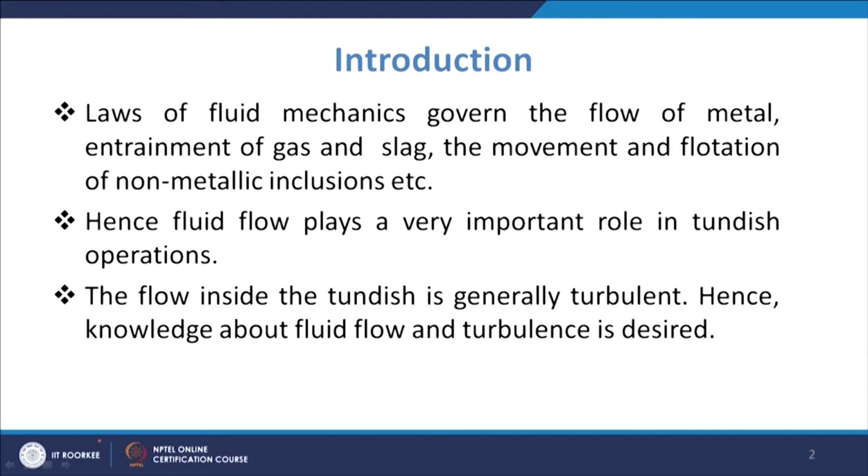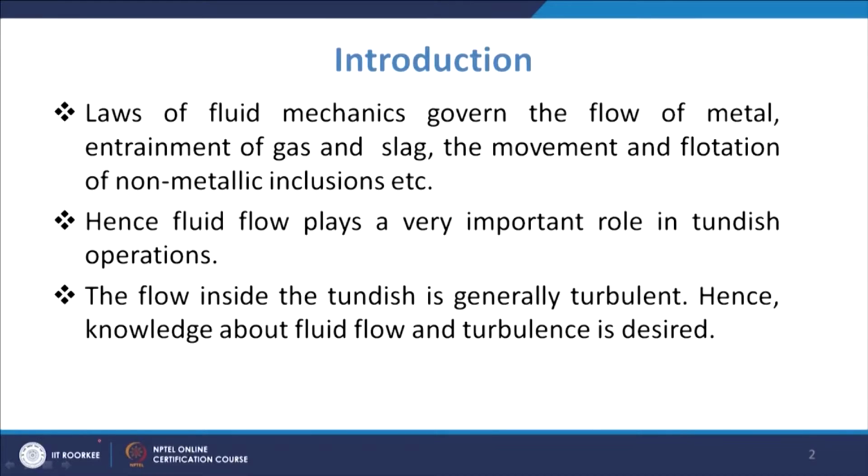So, as we discussed, in all these cases the laws of fluid mechanics which govern the flow of metal will be important, and that is why we need to understand the fluid flow behavior, especially if you talk about the tundish. In the tundish you have different regions. There is a region where the liquid metal is coming from the ladle, and then you have the remote regions also. In most cases, the tundish flow is generally considered to be turbulent.